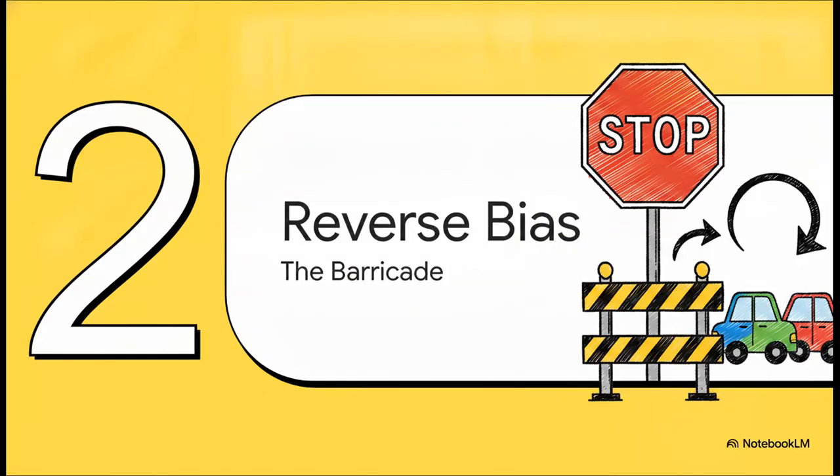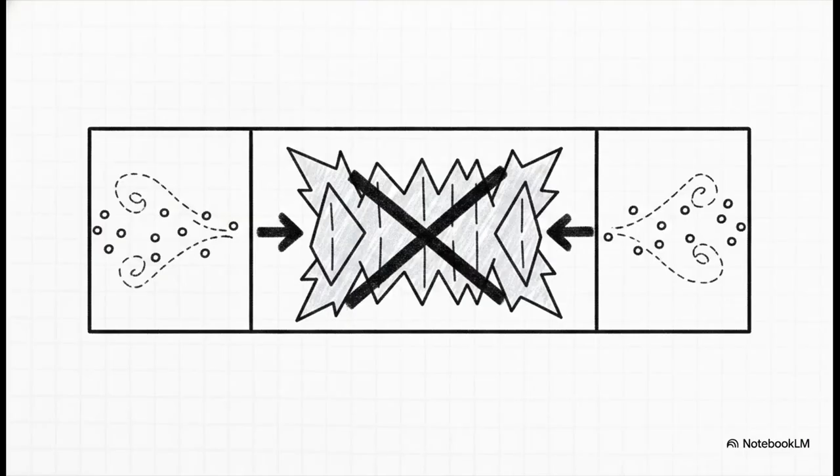Okay, moving on to the other side of the coin, reverse bias, the barricade. So, what happens when we actively want to stop traffic? Well, by simply flipping the battery connection, so the positive terminal is now on the N-type side and the negative is on the P-type side, we completely change the internal physics. This applied voltage is now supporting the built-in junction barrier. It's literally pulling the charge carriers away from the center. So the depletion region gets wider and wider, acting like a really thick, reinforced wall that completely blocks the main flow of those majority charge carriers from crossing over.